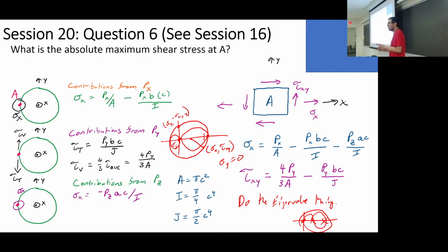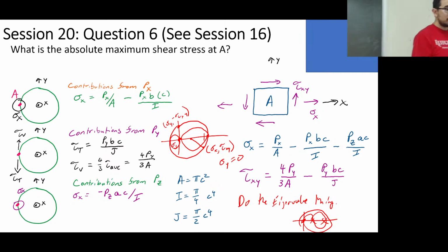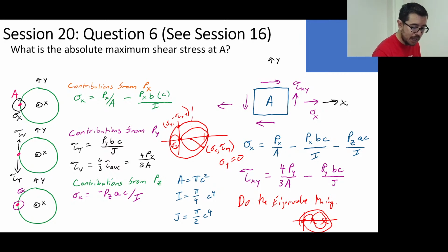So, go back to what is the general process for creating a Mohr circle? You find the center, you plot your reference point, you find the radius between them, and then you can construct most of the rest of the circle. Correct. So where is this circle? Where is the average?